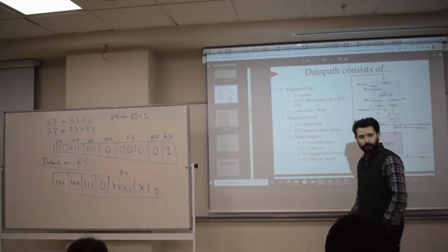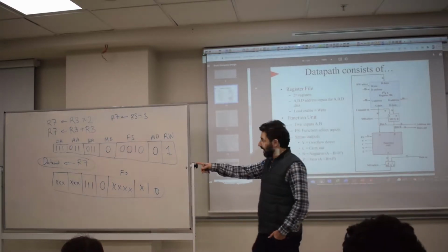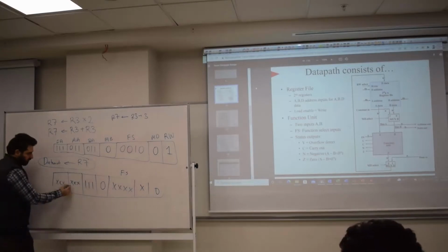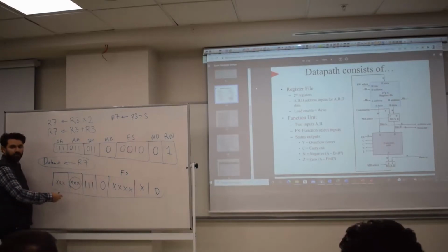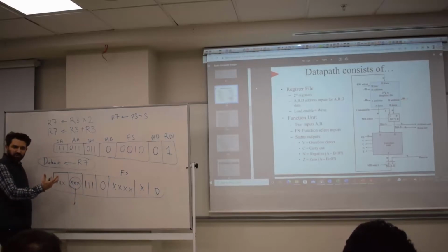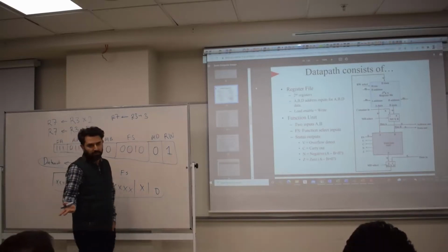When we receive address out, I just used it. Without using an address, you cannot write data, right? I just assume that this is a don't care. But in practice, as I said before, this is not a don't care. This is some register that has an address value that you would like to write to. Here I just said don't care because any address value is okay for me.